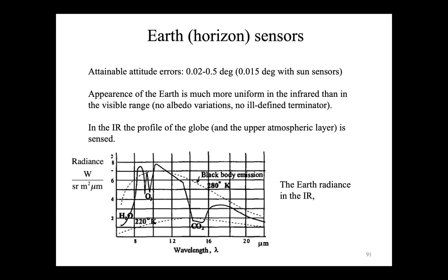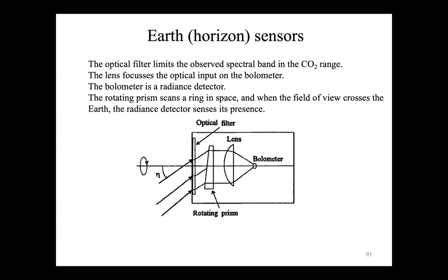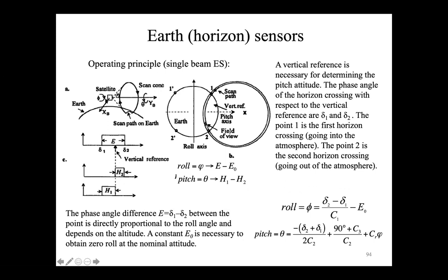So that's the reason why probably you don't need an extended Kalman filter or a QUEST algorithm, because basically what you need to do is to use the Earth sensor in order to determine the orbital frame, so your body frame with respect to the orbital frame of the spacecraft. So usually the case that you have is indeed a satellite that is orbiting the Earth, and you need to determine, for example, to keep the nadir pointing of the spacecraft.